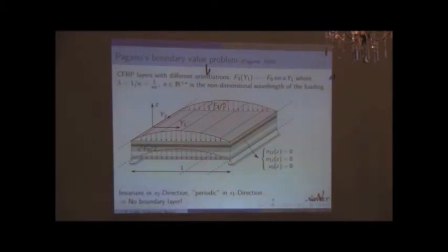And if you do that, you can perform a variable separation and solve analytically the 3D problem, and you have hyperbolic functions through the thickness and sine functions in plane. Okay, this solution has very specific features, and that's why it's a closed form solution. There is no boundary layer because it's not clamped. It's a simple support, so no boundary layer. It's important because after I will compute some convergence estimates, and this point is critical.